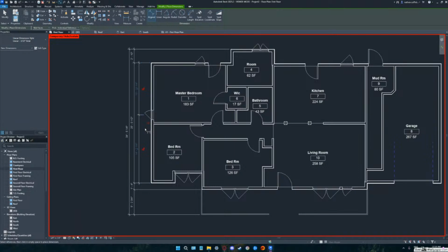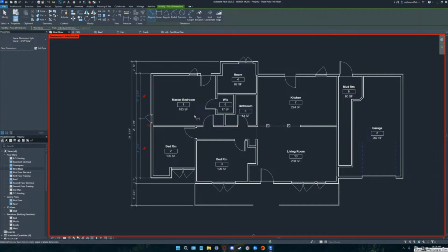Then you would run some dimensions through your building and pick up all the interior wall locations. And unless the people that we're working for want to snap to the exterior or the outsides of the windows, I always go center because it's one less click. Okay.